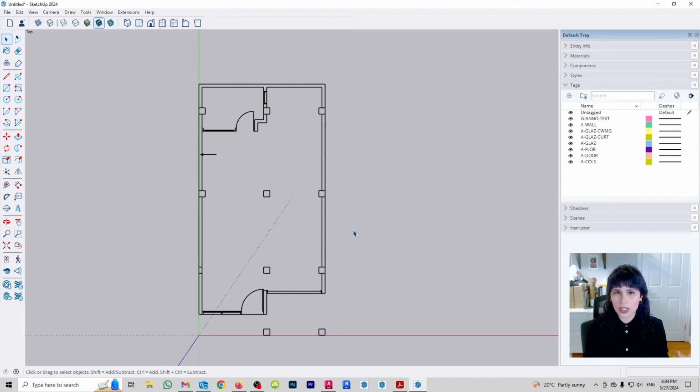The CAD drawing was set up properly, which meant that when I left my SketchUp importing options in model units, SketchUp was able to convert the AutoCAD file from millimeters into feet and inches. But you're not always going to be this lucky. AutoCAD users are the Wild West, and some people do not understand how unit systems work in AutoCAD.